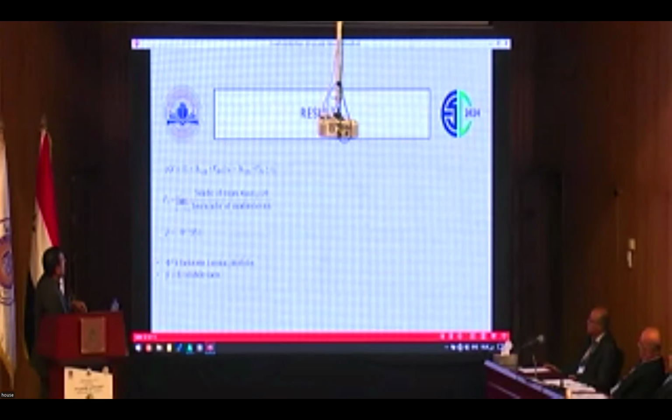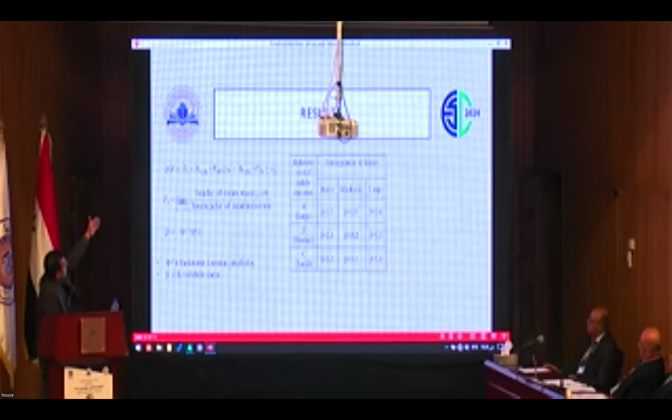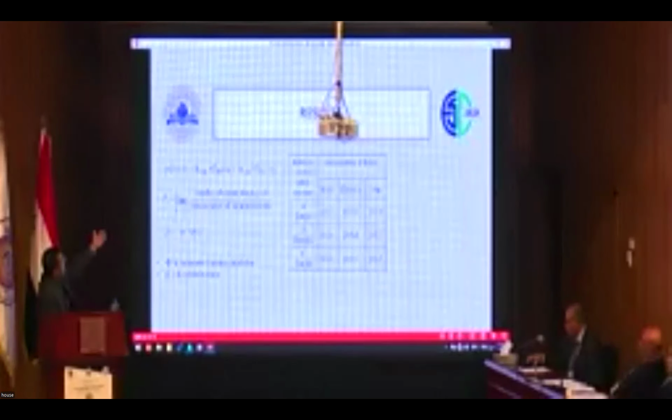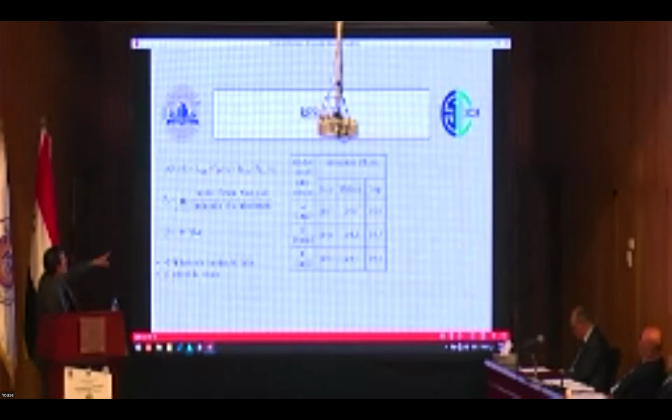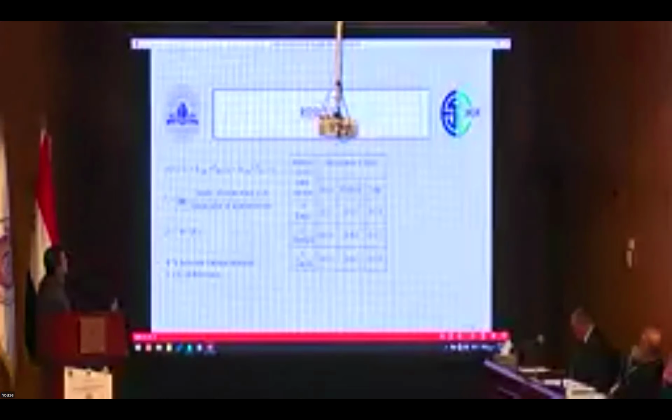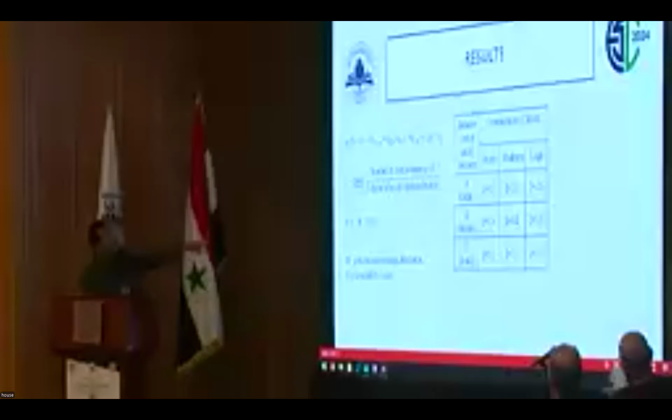From this model, we count the number of failures. The number of failures divided by the total number of trials shows the probability of failure, a few out of a million. This number is very small, and working with it is a little bit difficult. So sometimes we use the inverse Gaussian distribution, minus inverse. It gives us a number that we can compare with codes.